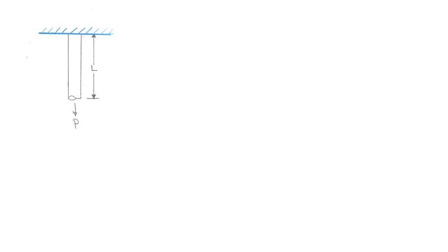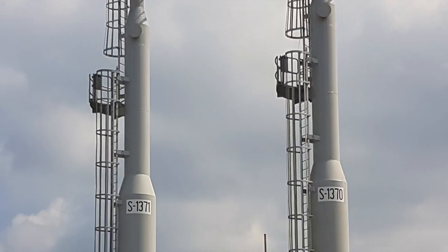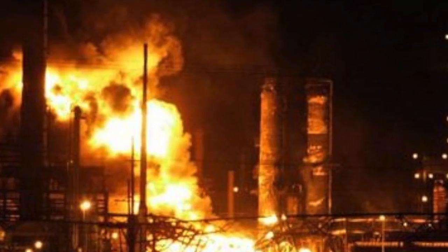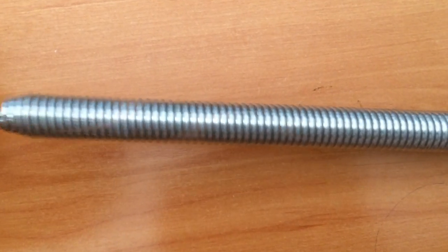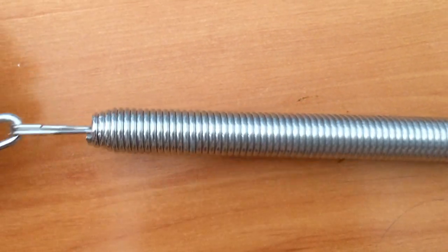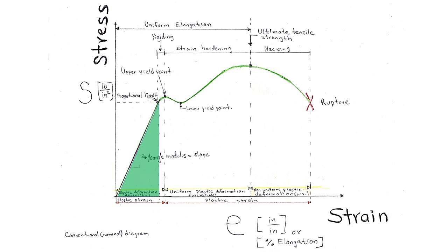When we work as designers, we set limits because it is undesirable to have materials expanding or contracting more than necessary or breaking into pieces. This is because such deformations may compromise a proper lining up between structures and lead to equipment damage or catastrophic incidents, just to cite a few. Therefore, it is highly desirable that a deforming material recovers its original shape. This ability is usually referred to as elastic or reversible deformation.